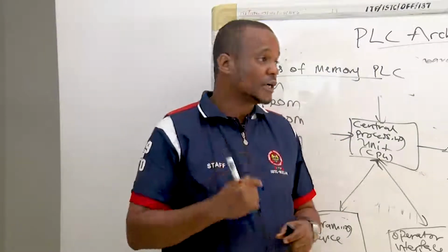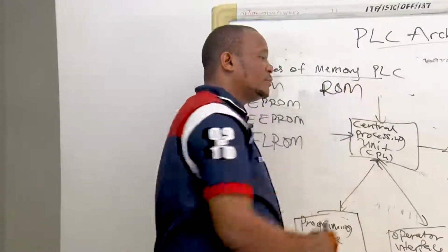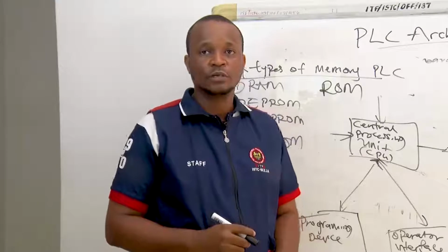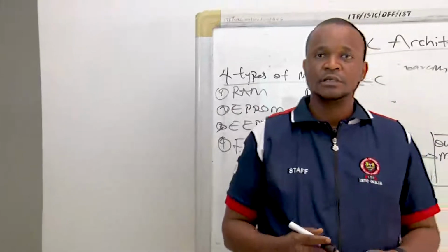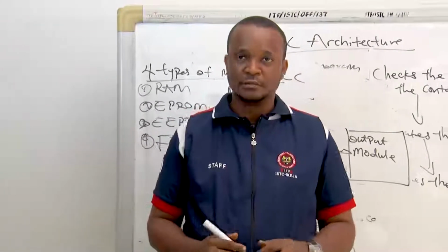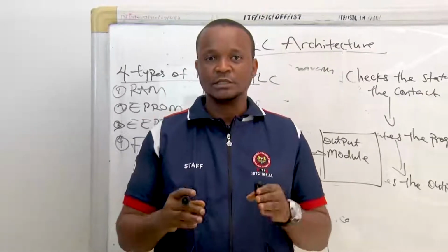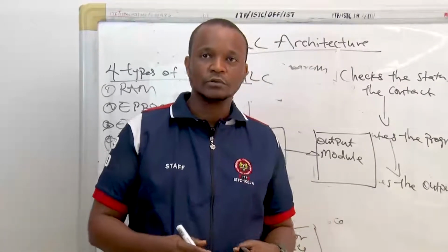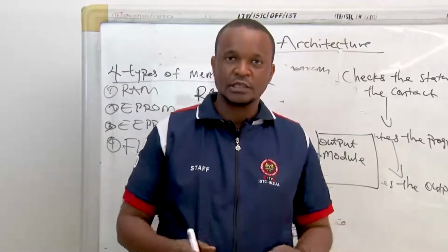Whereas the PLC manufacturer utilizes the ROM, that's the read-only memory, to store information about the PLC. Some of this information is what we call the executive information. And what is this executive information? It is composed of a permanently stored program that directs all system activities contained in the PLC. That executive program will tell the user program how to run, and handle communication with other peripherals that are connected to it.